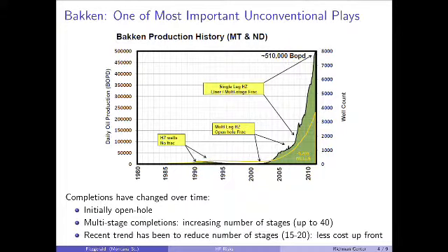And so really it was in the early 2000s when you had multiple horizontal boreholes, multi-leg horizontal wells, and what they call an open hole frac, which is probably the easiest way to describe that would be you take the water that Chuck was talking about, you dump it down the hole, you pump it up, and the fractures go where they go. You don't necessarily know which direction they're going, but you're going to crack those rocks. The results turned out to be quite good. They were free-flowing wells with a light sweet grade of crude. This encouraged operators to come back and try to refine that technology.